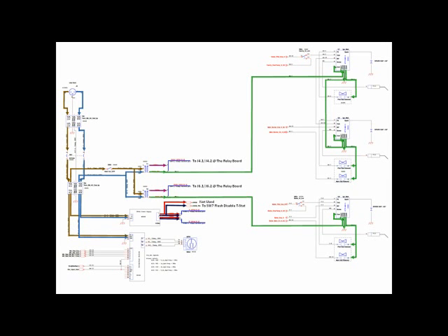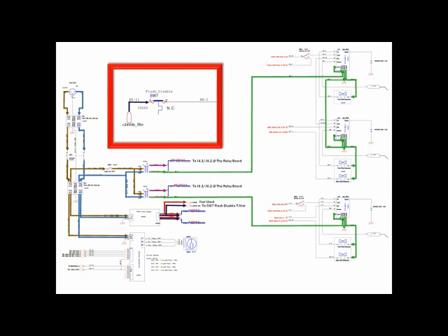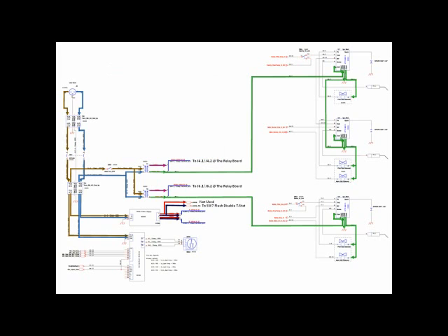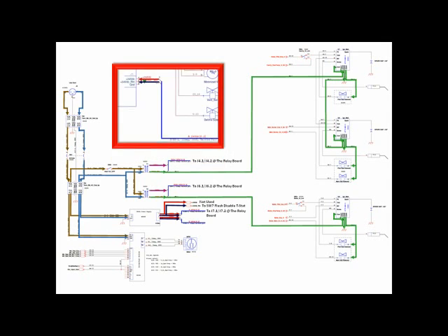It supplies several locations. We will first look at the flush disable thermostat it supplies with 24 volts DC low, or negative 24 volts DC. Next, the power supply sends 24 volts to the relay board's terminal J7.